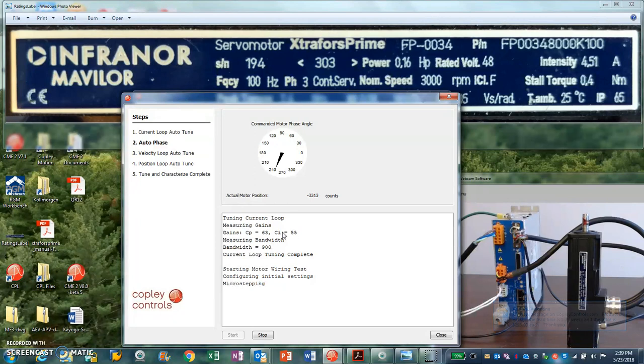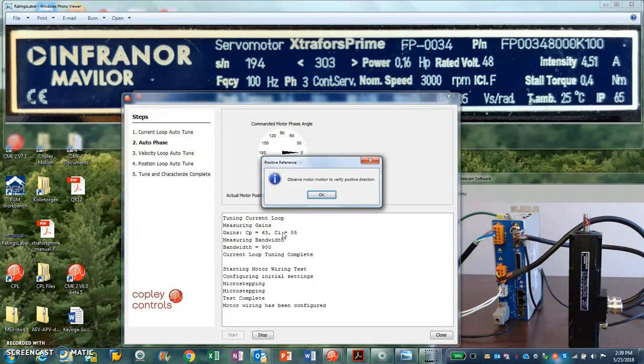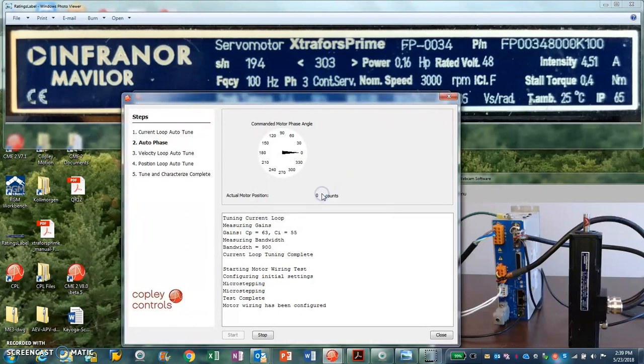So this is open loop microstepping. It's trying to determine the phase. It's kind of hard to do that test connected to a load, so my recommendation is disconnect the load. Although it will apply sufficient current, open loop, still a load may hinder some progress there.